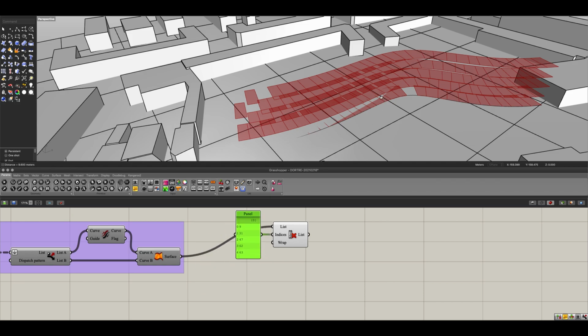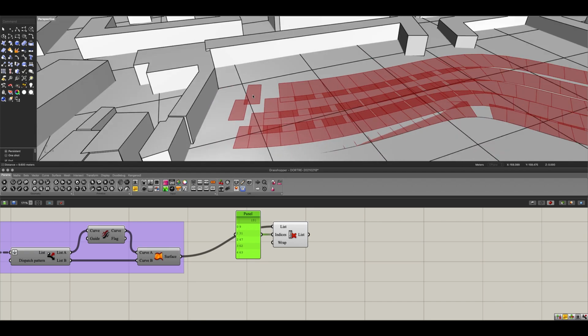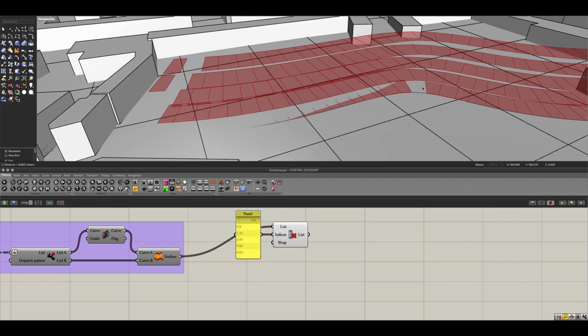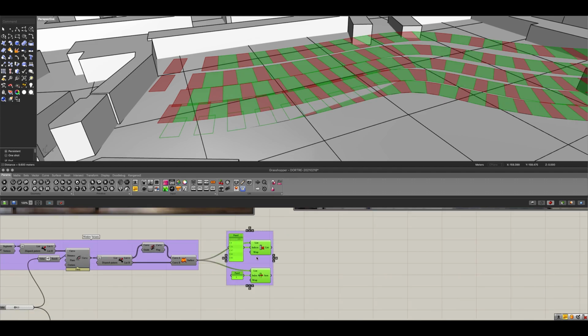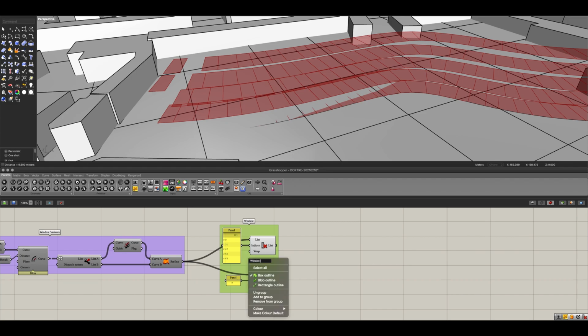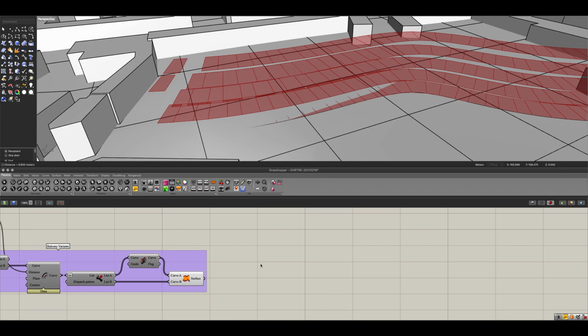As you can see here, we've managed to remove this central piece here, and also many of the pieces that block us from making the stair effect. Of course, we want to repurpose this for our entrance variant. So all we need to do is add in list item, and now we can add in double-9, since this is the plane that we want to isolate completely. Okay, so now let's group this up. I'm going to name this one window filters. Down here we're going to use the same process, except with different values.